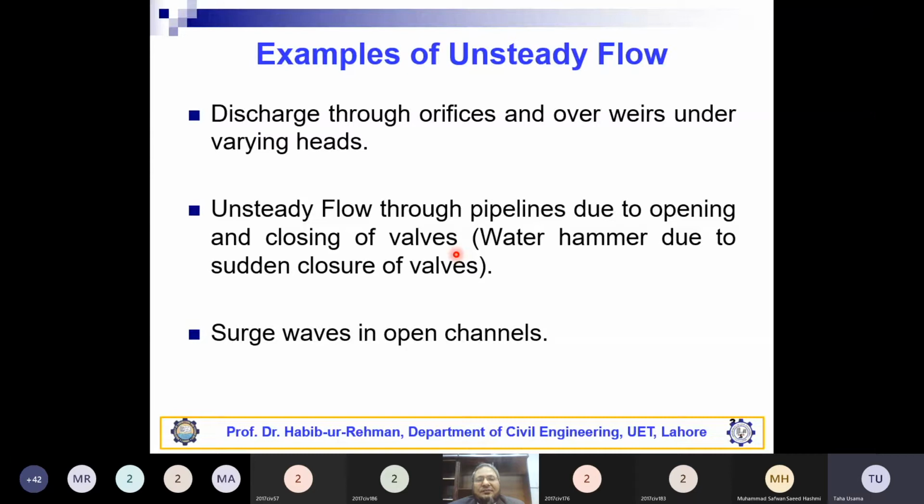Oh yes, the spear-headed needle. This spear-headed needle moves in the axial forward direction and closes the opening of the nozzle. And what is the example of the valve in reaction turbines? Movable guide blades. Very good. Those are movable guide blades.